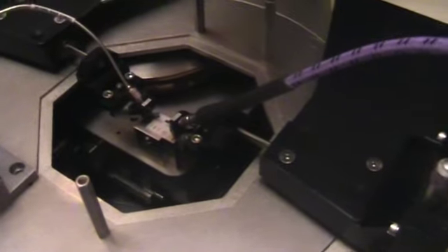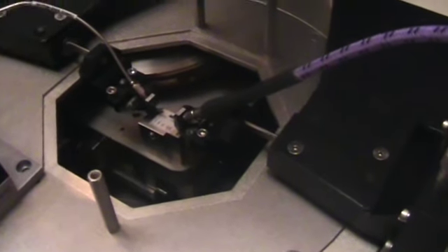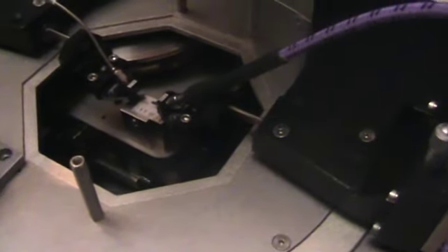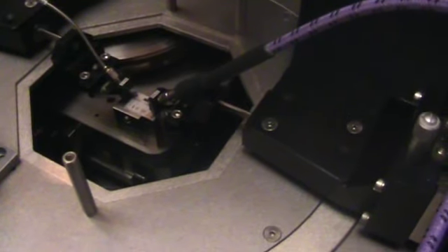So we'll be taking a number of measurements from the left side of the tuner down onto the reference plane just past the probe tips. So we'll go ahead and get a calibration down at the probe tips and make a couple of de-embedding files to get ready for the tuner cal.